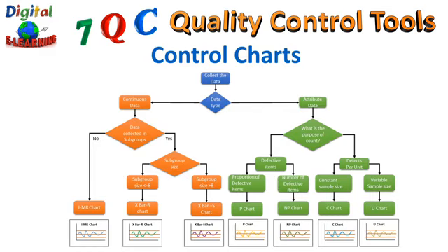So we normally have two types of charts under defects per unit: the C type control chart and the U type control chart. The C chart plots the number of defects over time. Here the area of opportunity must remain the same over time. And the U chart plots the number of defects per inspection unit over time.